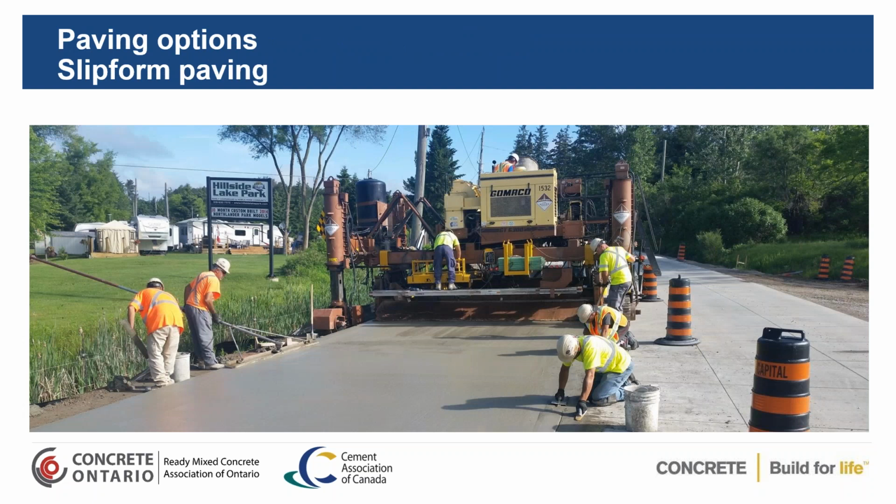So when we're looking at slipform paving, so that's fixed form paving now. So it's a fairly simple process. The amount of equipment that's required is minimal, but you have a more labor-intensive crew. Here we're going to go on and talk about slipform paving. These are for higher production areas. And you see here, there's your slipform paving machine. It's a very high production, and because of that, you're going to actually deliver the concrete in a little bit different way as well.